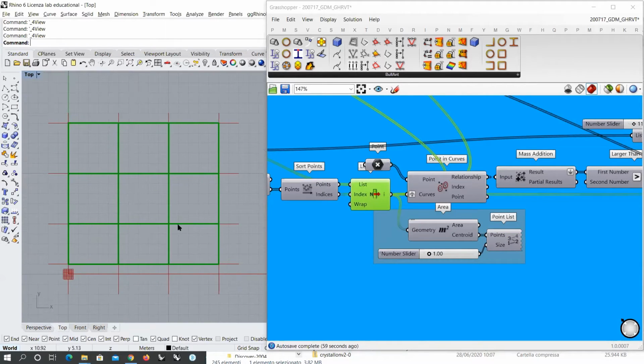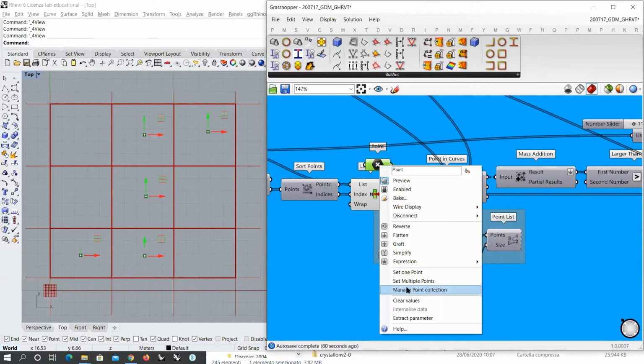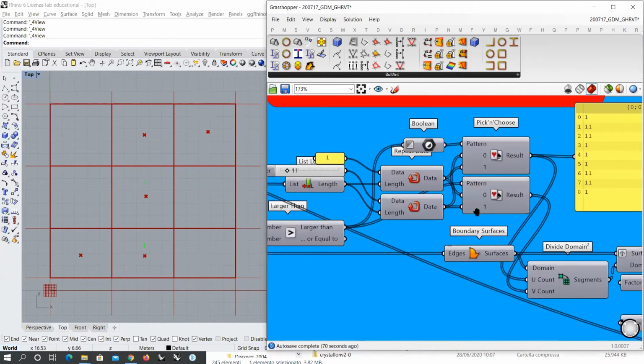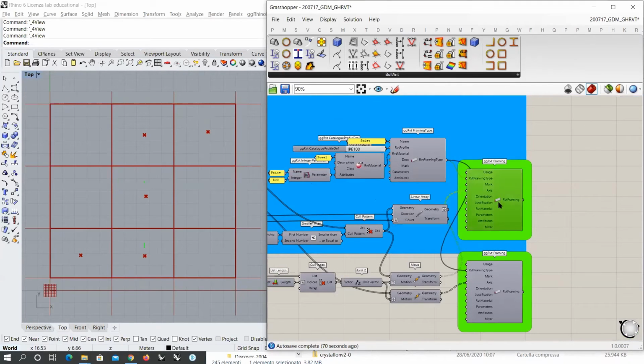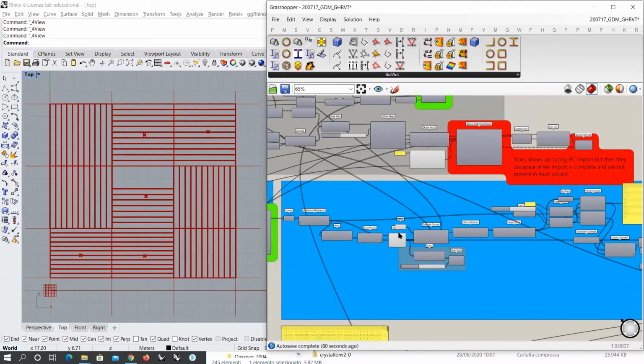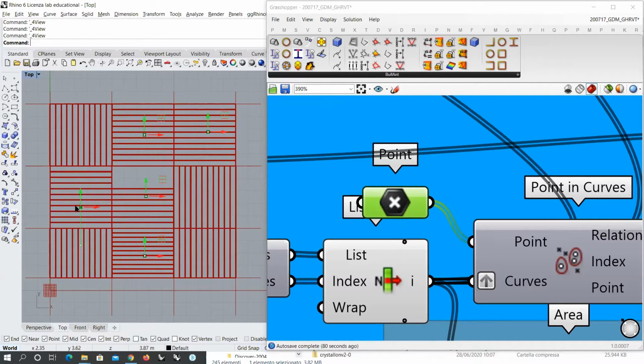Well, this is some manual operation. I took a point container and specified this set of points by setting multiple points. Let me show you the final result again. Here the secondary beams are visible. The result of this work is that if I grab, for example, this point and move it here, you see that the orientation of these secondary beams has changed. So you can decide what orientation the secondary beams have for each region of this floor.